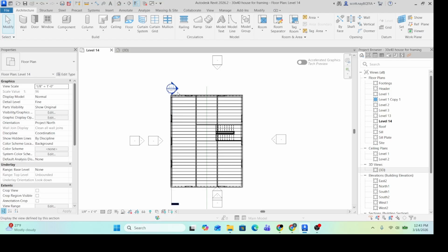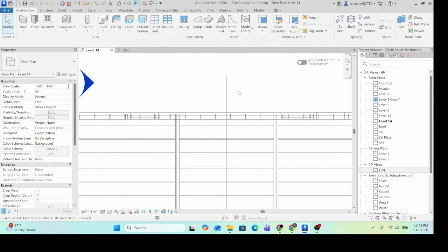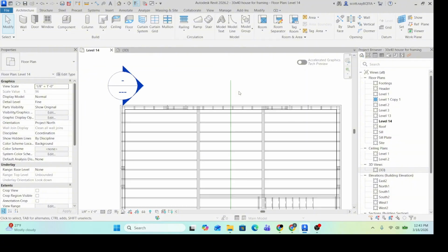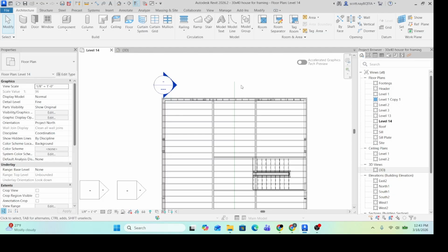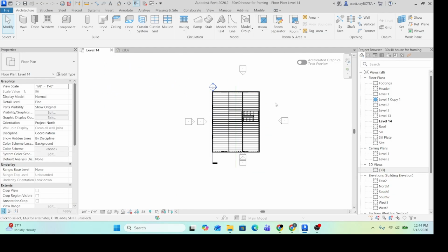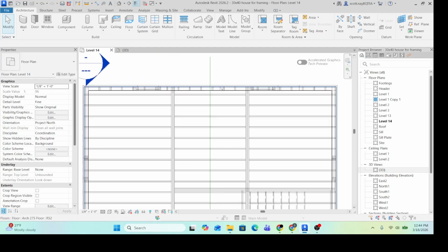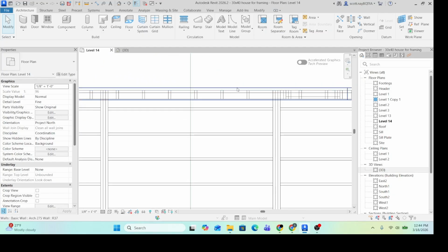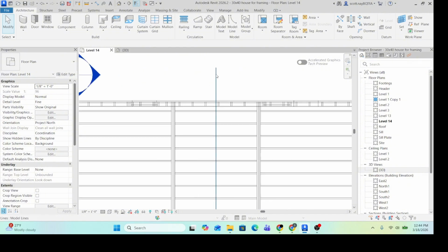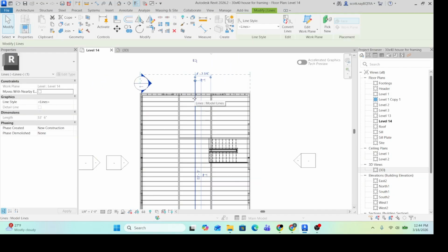Alright, so it turns out that Revit does not play nice with gable roofs and creating parts. It can do it on a shed or a flat roof. So your only options are either create a midpoint like this, and do half your roof, do half your roof, and then do them individually as parts. That creates issues when you're doing attached top base with the walls. So I'm not actually going to do that. I'm going to go ahead and delete this, but depending on how your layout is, you might want to give it a try.